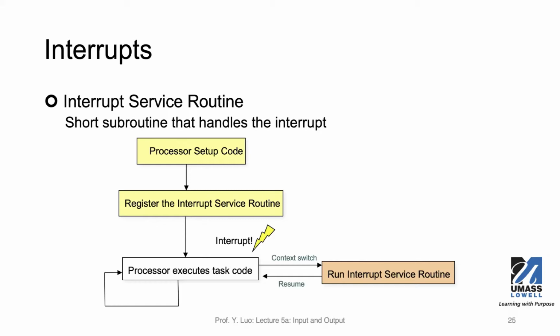So this interrupt could be different from case to case. And electrically, the interrupt could be level-based or trigger-based. So you could raise the voltage level too high or too low, or generate a pulse. Both are possible.